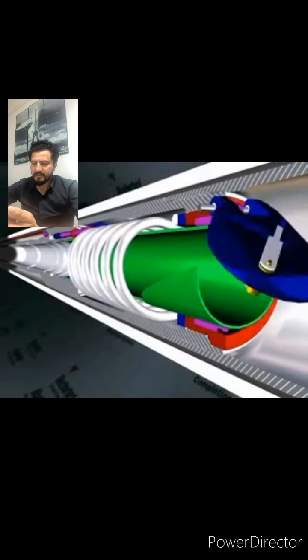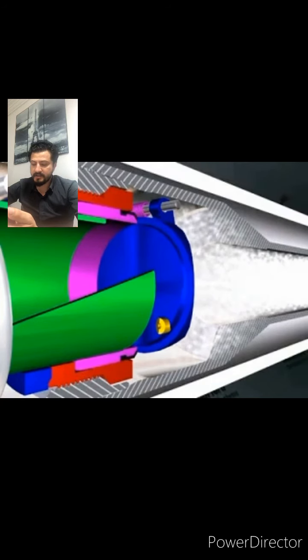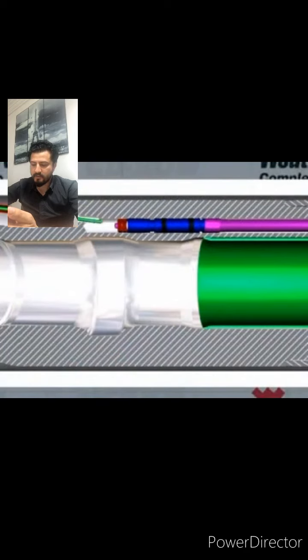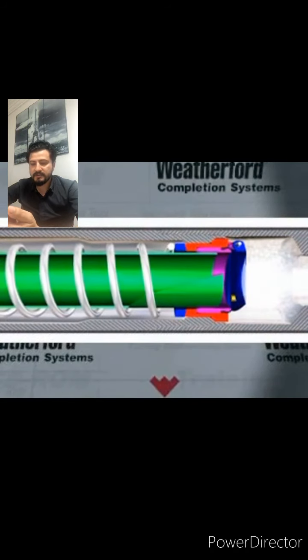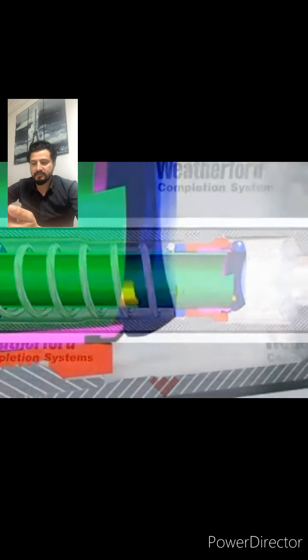In the case shown, notice that when there is pressure below the flapper, the force coming through the control line is unable to open the flapper. So this feature in the flapper is called the equalizing valve, to equalize between above and below the flapper in order to open the flapper to the complete position. As you're seeing, equalizing above and below the flapper allows it to open.